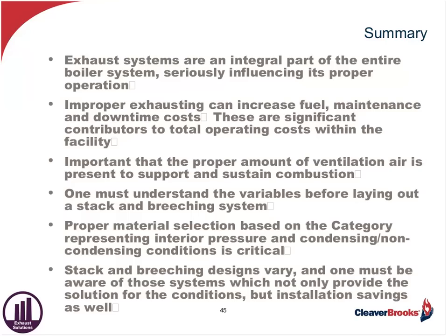Okay. Next question. With a forced draft boiler burner combination, how do you know what is the correct pressure within the stack, plus or minus, for the boiler to operate efficiently? That's an excellent question, and that's kind of what gets back to what I was mentioning before. What I would suggest that the person getting involved with the stack and breeching layout and design do is contact that boiler manufacturer, find out what they can live with for that particular model and burner boiler combination.